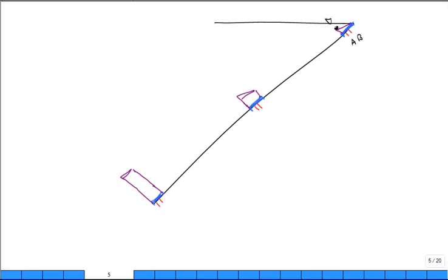True? So, when it was all triangle, the resultant force was a lot lower in magnitude, but where was it placed? At a third. It was placed right at a third. All right? If it's almost all rectangle, where is it placed? Very, very close to a half. So you're placed in between. I can't say real fast where exactly it is. I have to compare depths and angles and how long the plate is. True?